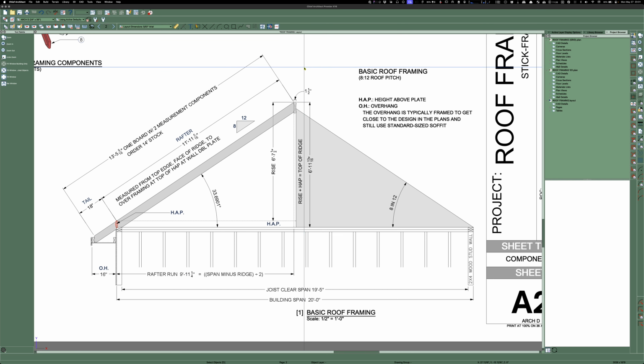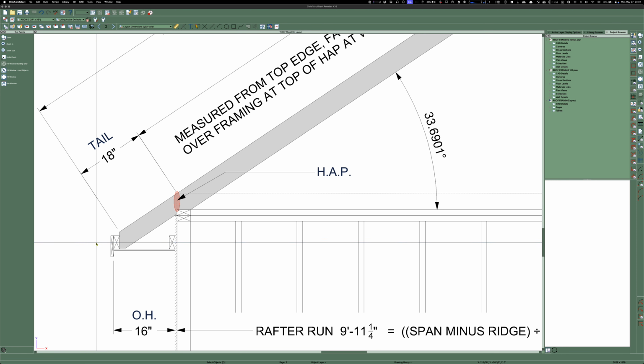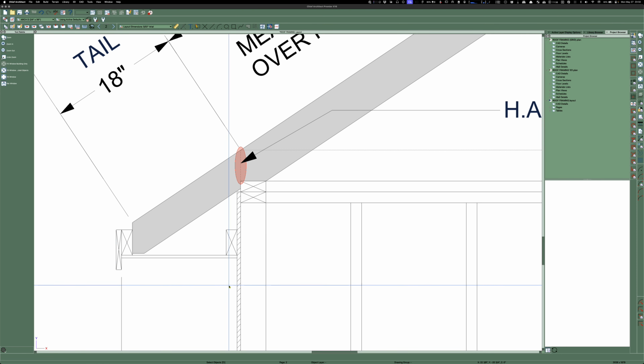So yesterday, after framing for 25 years and not even really thinking about it, I was working on this drawing right here, and it made me think of something. Look at this. This is wall sheathing, and I've got it stopped at the top plate. I didn't carry it up to the top of the double plate.